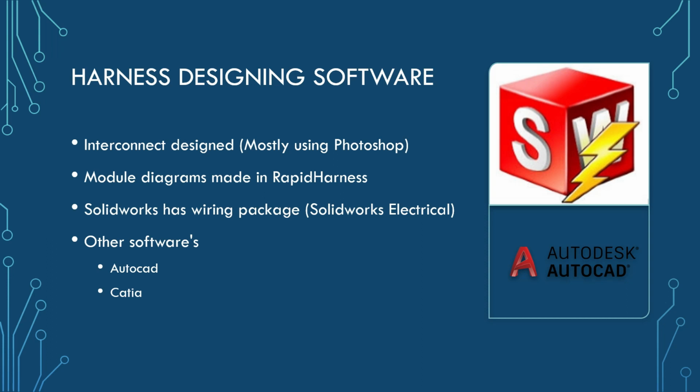Before I get into those though, there are a bunch of softwares out there that teams use. Some people even use SolidWorks Electrical, which actually routes the entire harness design you make through the car. It's a lot more complicated just because we haven't done this in the past, so it would be a bit of a learning curve. But it'd definitely be beneficial later in the years, especially since we do design the entire car in SolidWorks. Having that option to route it entirely in the car, get those lengths right off the bat, not having to wait for the frame to be built to measure everything, might save us some time down the road.